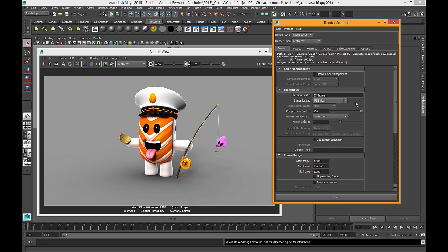The second reason you should render as images is if the software gets turned off or there's a power failure, like if someone comes and shuts everything down while you're away from your computer. Any frame that has already rendered has already been saved and exported into your folder before the computer renders the next frame. So it renders a frame, saves the file, renders a frame, saves the file, and so on.